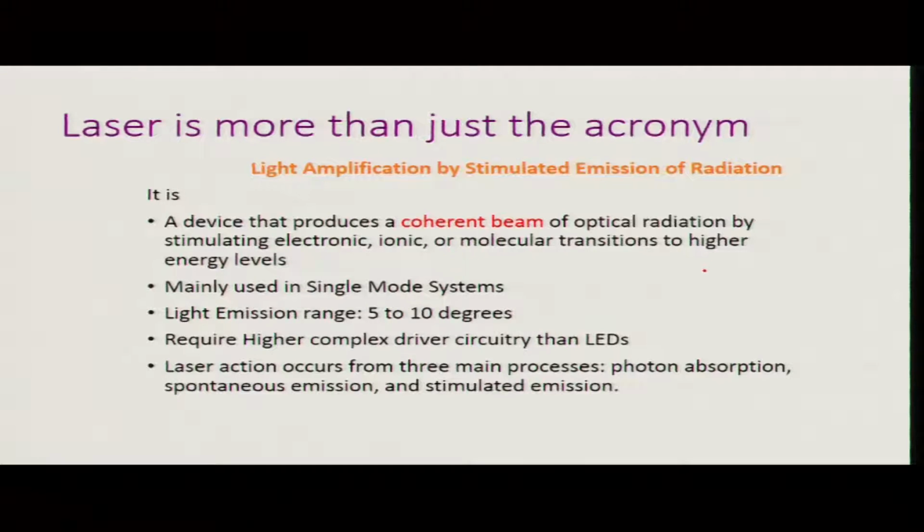It is mainly used in single mode systems. Light emission ranges from 5 to 10 degrees, which means that it is highly directional, and it does require a higher complex driving circuitry when we are looking at certain aspects compared to, let us say, the light emitting diodes.